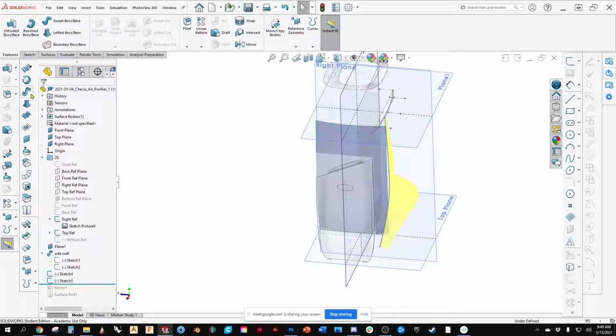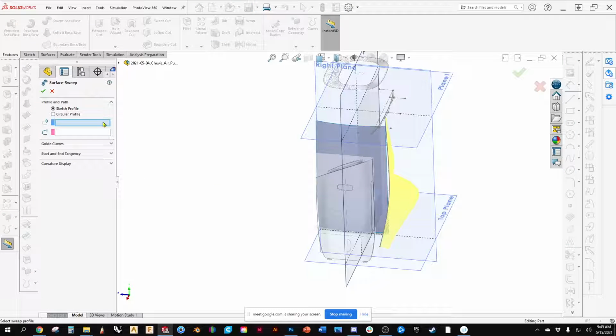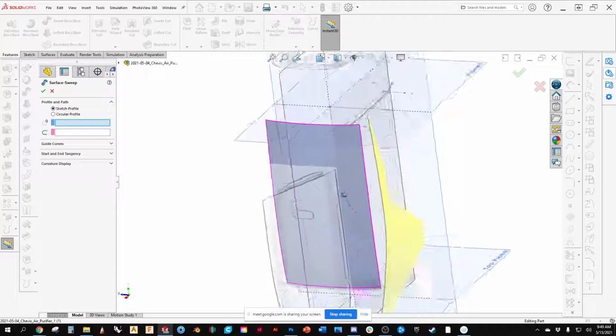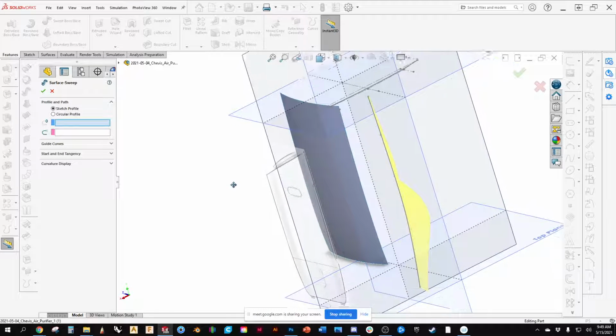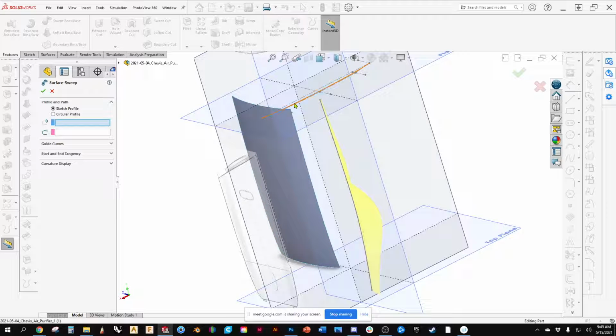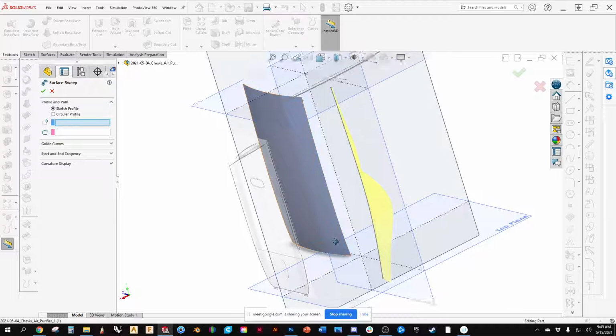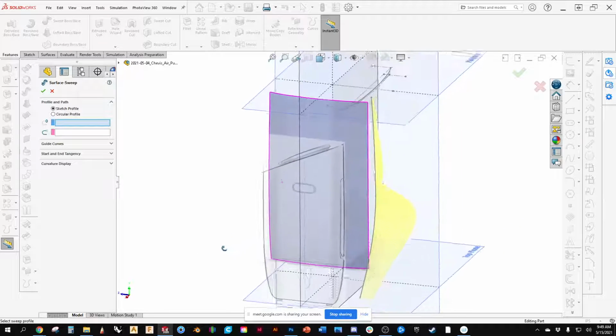Again, for this we just need the swept tool. Where you'd want more control, the swept tool gives us control at the top and the path it follows. If I want more control on where those edges are, then I would use a boundary, where I would control the top curvature and the bottom curvature. Did we go over that last week? It's hard to remember if I went over this with you or one of the videos I've been watching.